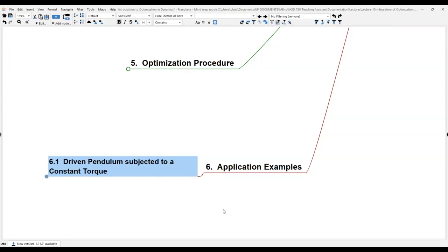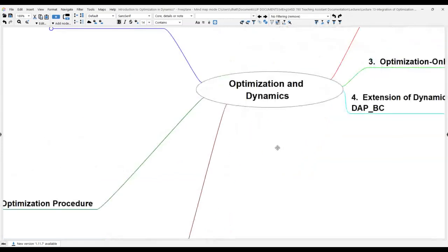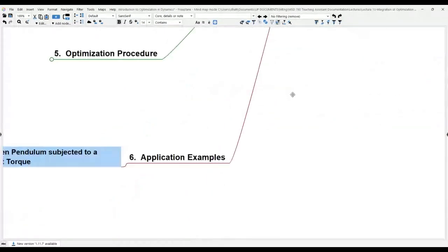If you choose your initial design in a savvy manner, then it will still converge to some sort of solution. It might not be the global optimum, but it will most likely converge to a local minimum. So it's basically just changing the dimensionality of your problem. It's not anything major. It's just removing that as a design variable and then rerunning the optimization. So I think that concludes the example that we're going to look at today.